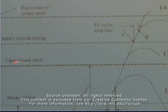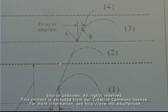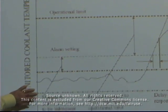Then you have below that operating limits, which are where you don't want to strain the reactor, but this is sort of what we would call your administrative limit. You don't want to be in this zone. Your alarm set points are much lower, and your normal operation could be down in here.